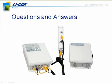Some people have thought about, what if I permanently seal the shroud in there? Well, then you have some issues with different materials. For example, the shroud is made of PVC and a different kind of metal than the rest of the head. During hot and cold temperatures, things will expand and contract at different rates, and you could cause some physical stress to the head.